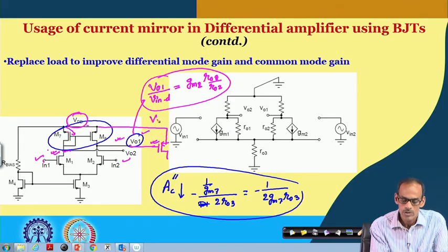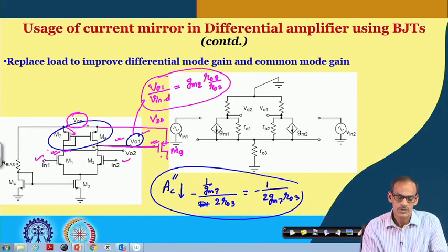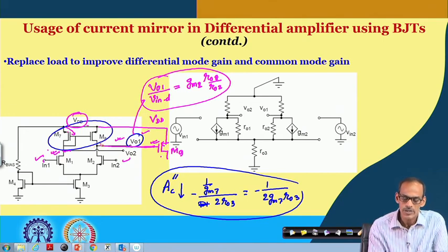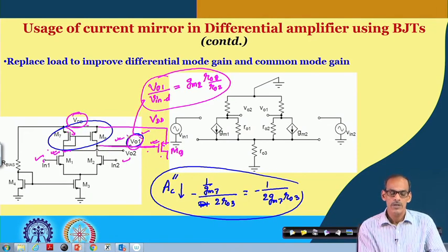So, we can have this VDD, and let us call this transistor 9, and this transistor 9 is having a very meaningful DC voltage received from the drain node of transistor 8, and of course, it is also receiving the signal which is coming through this VO1.